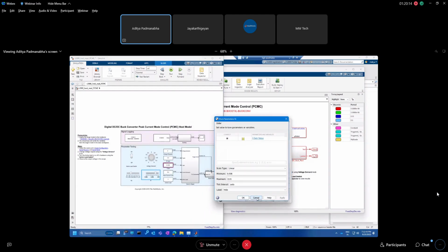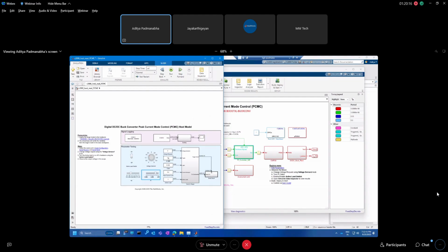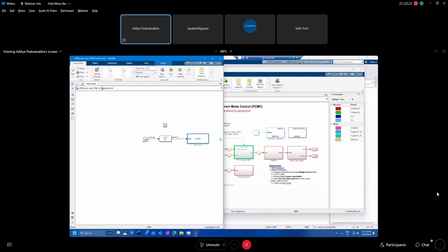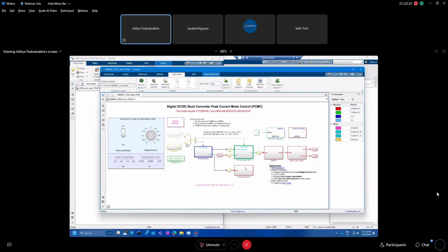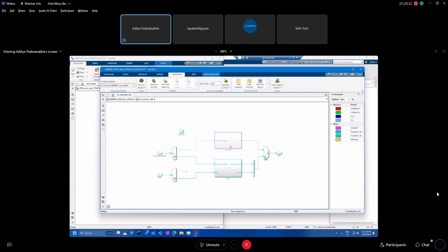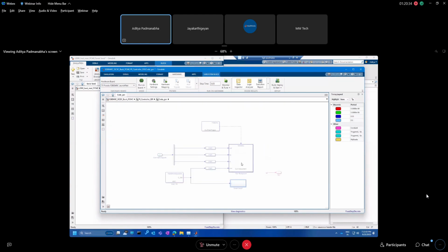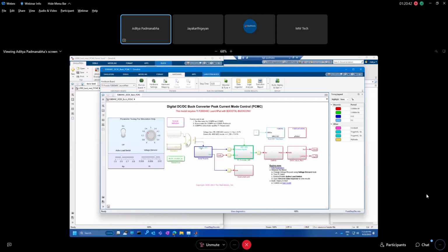Whenever we change the sliders, these values will be sent through serial send to the target, and here we are receiving in serial receive all the data points, and then we use those data points as part of running the routines for code gen. So if you can see, these KP, KI gains are coming from the serial receive.